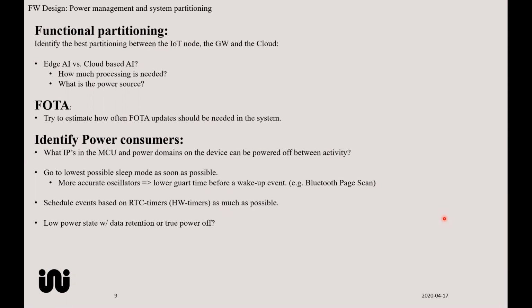So, low power state versus data retention. This is more relevant when you talk about a Linux system or an Android system where hibernation mode is possible. For some systems, the booting will consume a lot of power. Typically, a Linux system or Android consumes quite a lot of power when you boot. And then when you're up and running after a lot of time, because it takes many seconds to boot a Linux or an Android system, then you can start being active.